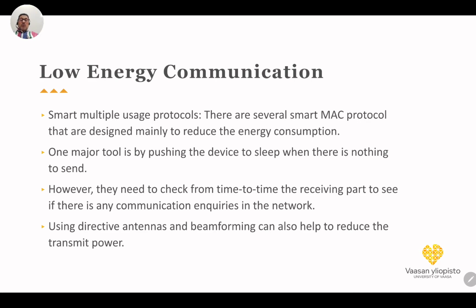Low energy communication, as we mentioned, concerns the transmission, but also the MAC protocol, where we should use protocols which force the device to go to sleep when there is no transmission. So we don't need to have everything awake inside the device. There is a control that makes it go to sleep to save energy.